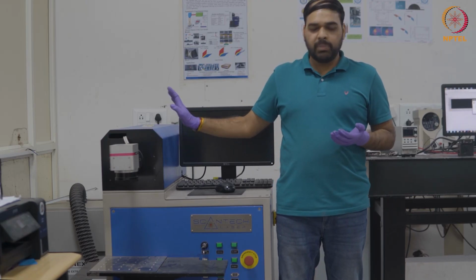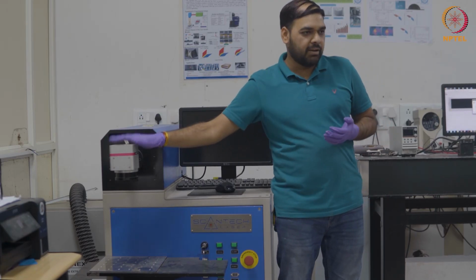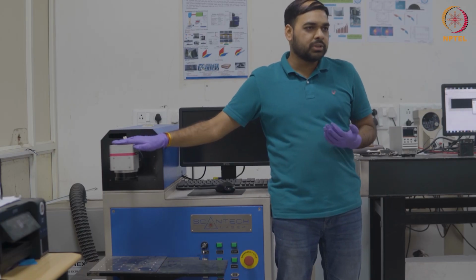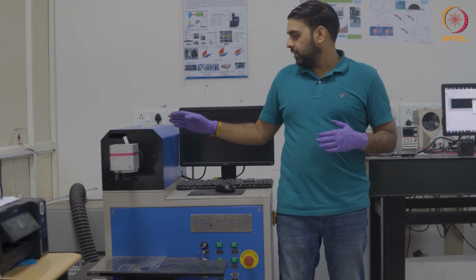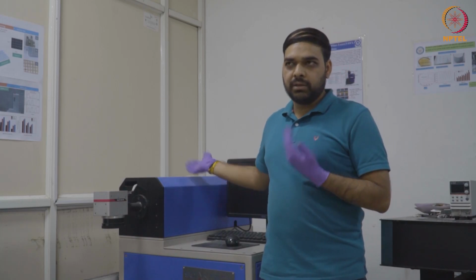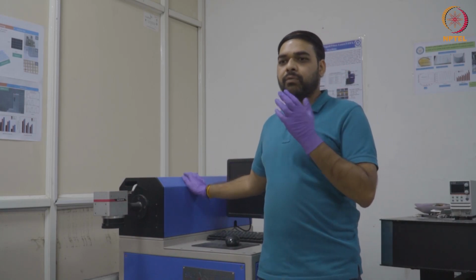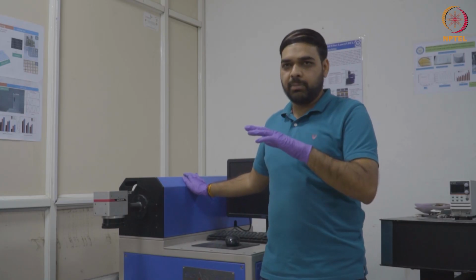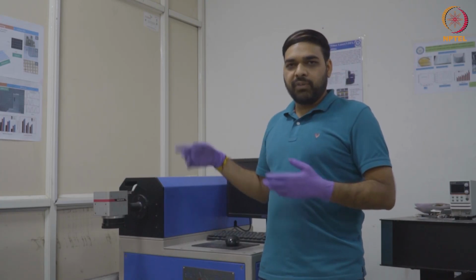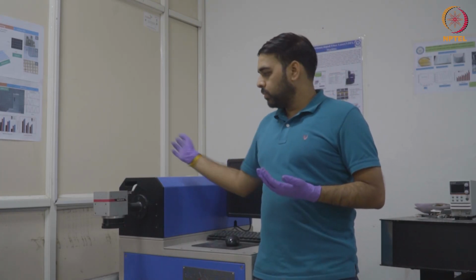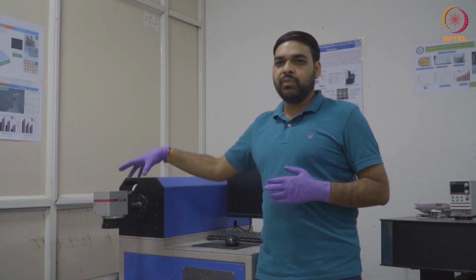The better point in this is we have a galvo here. That galvo controls the position of the laser beam which is coming through, and it is always in focus position itself. The basic thing in a fiber laser is it has a fiber laser source, an optical fiber, which is a lasing source. It is pumped through a diode laser, and it amplifies the diode signal to produce a laser beam, which then reaches the galvo head, where we can move it with the help of a moving coil mechanism.